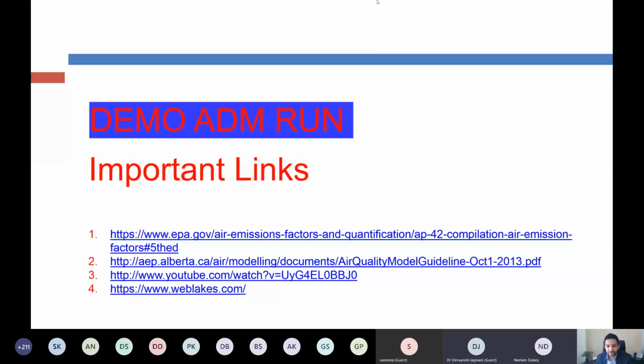Okay, thank you very much, sir. Sir, this is Devanshi. So these instruments measure the particulate matter directly? Yes, it can measure the particulate matter directly for different fractions such as PM10 and PM2.5 both. And when we measure particulate matter with the gravimetric method, we only get one value for the entire duration, like for a 24-hour duration, we will only get one value. That's an average value, I suppose. Yes, so a 24-hourly average value.